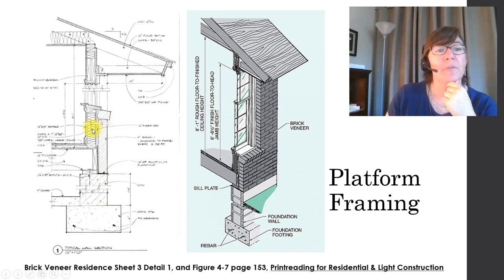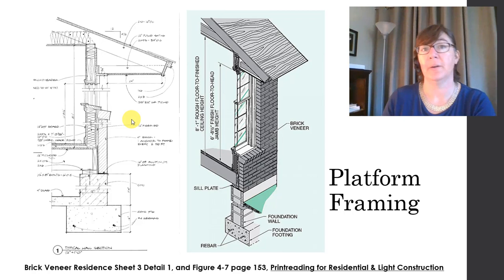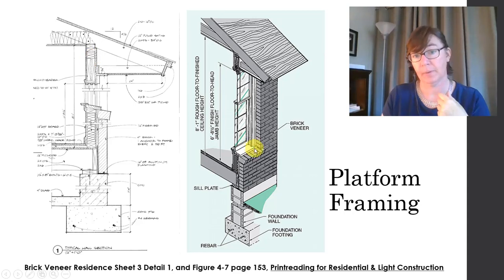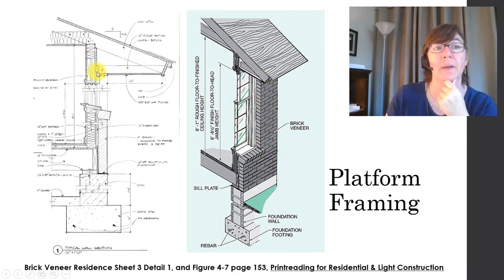Okay, so moving up in our wall, we see we're cutting through a window. Look at that. All right, I'm going to talk more about how to frame doors and windows next week in our doors and windows section. Okay, so we're going to skip over that for today. Moving up in the wall, this right here is the header for that window. And here's a little gap. Beyond would be the wall studs beyond the window. So in this section over here that doesn't have a window, this would just be straight studs behind there.